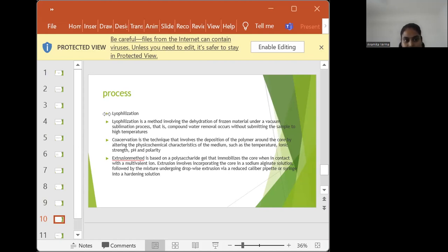First is the air suspension method. Microencapsulation by the air suspension method consists of dispersing solid particulate core material in a supporting airstream and spray coating the air-suspended particles. Within the coating chamber, particulate core materials are suspended on an upward moving airstream. The chamber design and its operating parameters influence a recirculating flow of the particles through the coating zone portion of the coating chamber, where a coating material is sprayed onto the moving particles. During each pass through the coating zone, the core material receives a coat, and this cyclic process is repeated depending on the purpose of microencapsulation. The supporting airstream also serves to dry the product while it is being microencapsulated. The drying rate is directly related to the temperature of the supporting airstream used.